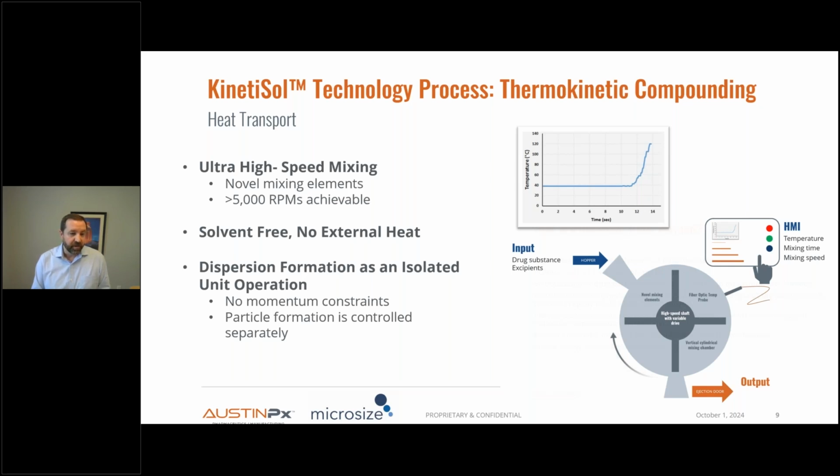KinetiSol is a thermokinetic compounding technique that utilizes ultra high speed mixing elements that operate at extremely high speeds, producing significant amounts of shear. This is a solvent-free process. This shearing and frictional heating that occurs when these blades impart energy into the product produce the heat directly and allow for the material to rapidly heat up and produce an amorphous dispersion.